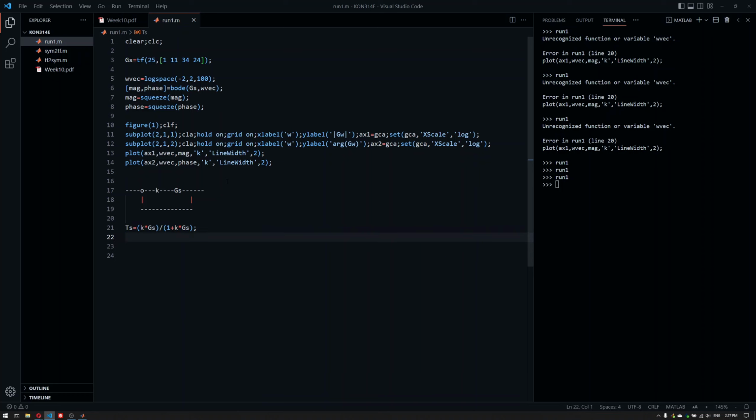Now, in order to analyze the behavior of the closed loop or the open loop, all that we need to do is transition from the Laplace domain into the Fourier domain. So what we are going to do is substitute s equals j omega, basically. And if I do this, I can just call everything like this here. Now, what is stability?